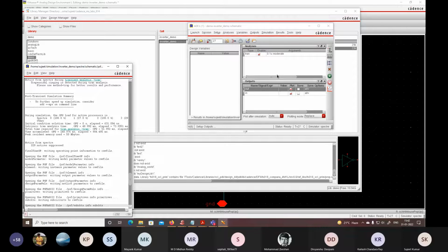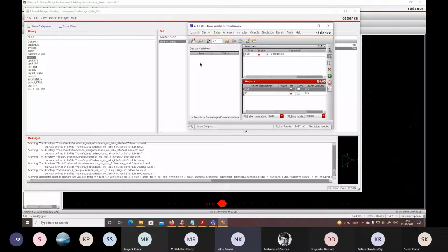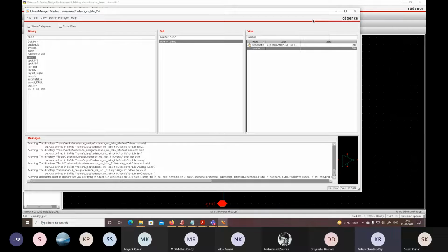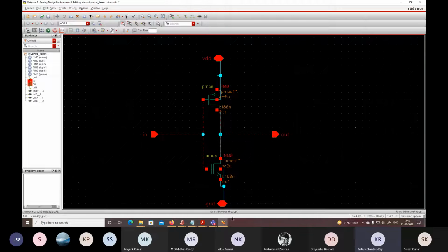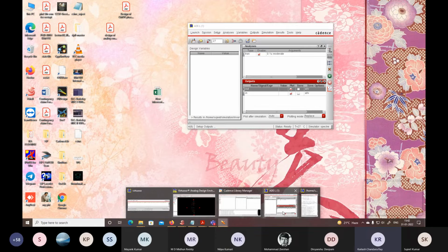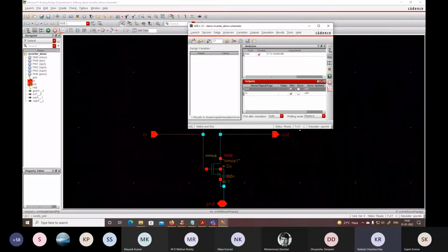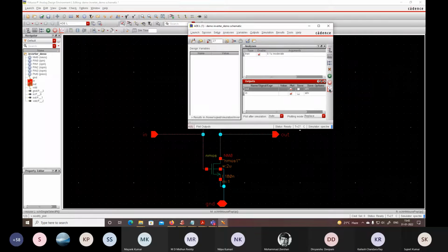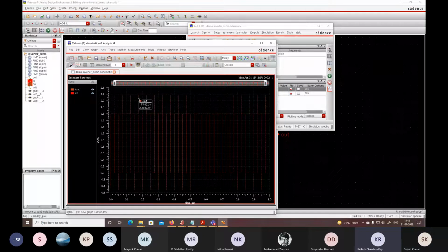Sir, this spike. This spike is coming due to charging and discharging of the capacitance of this MOSFET, because of the different aspect ratio. The aspect ratio decides your resistance and capacitance in the path. Second is the input rise and fall time. If you have a sharp rise and fall time, there is a chance of a spike. So that affects both the rise and fall time of your input vector and also the aspect ratio of your devices.